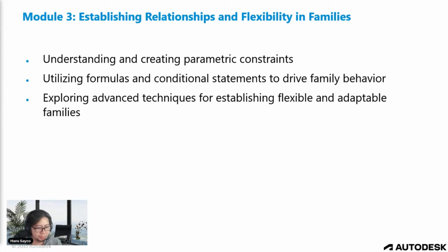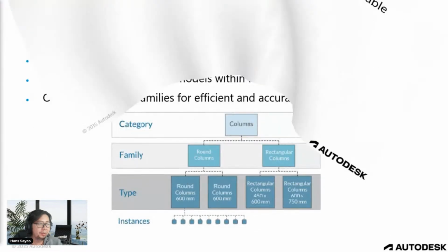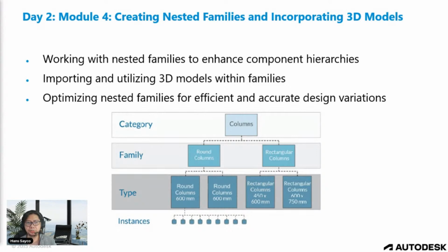So we have some types. And for the day 2, just to share with you, the day 2 is creating nested family incorporating 3D models. So although we have inserted our 3D model on the project, that's one sample, and importing, utilizing 3D models. May nagtanong last time na how are we going to import models from different CAD or 3D models. So we just insert it and create a family from there. Optimizing families for efficient and accurate design variation.